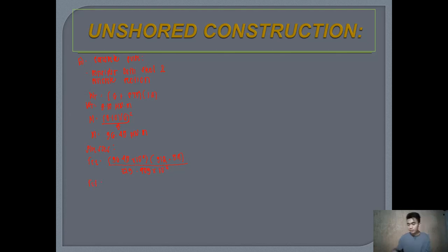FCT now will therefore be, input that on our calculator, that is now 36.45 times 10 raised to 6 times 312.59 all over 723.903 times 10 raised to 6. So I will have here 15, we check first, all right. So that is 15.74 megapascal.